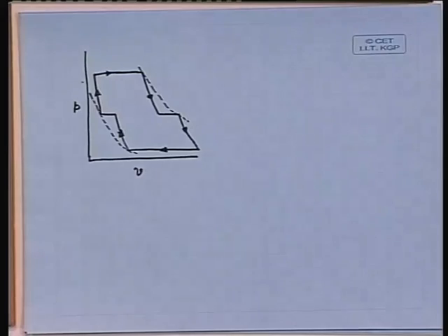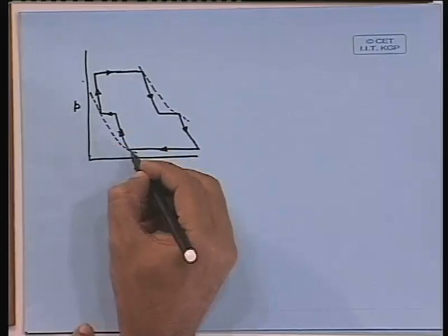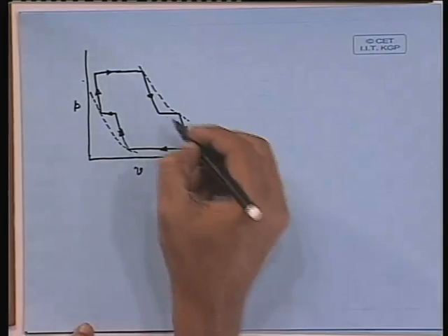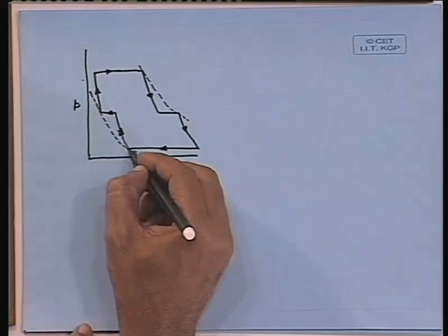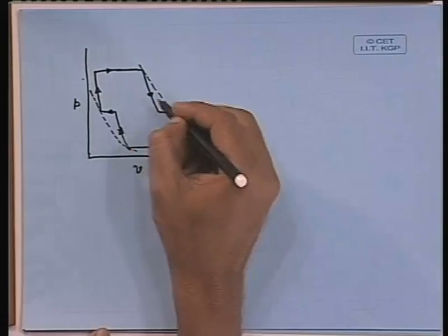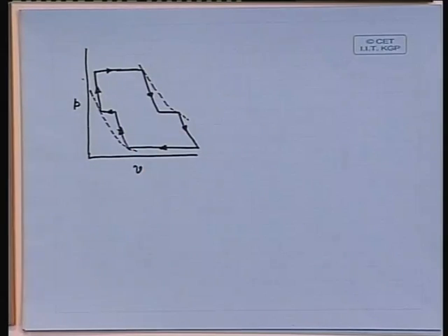All right. So, one is the isothermal line here and another is the isothermal line here. After reheating we are coming back to the same temperature, and after intercooling we are coming back to the same temperature with which we have started our cycle, and here also after reheating we are coming back to the same elevated temperature at which we have started our expansion.